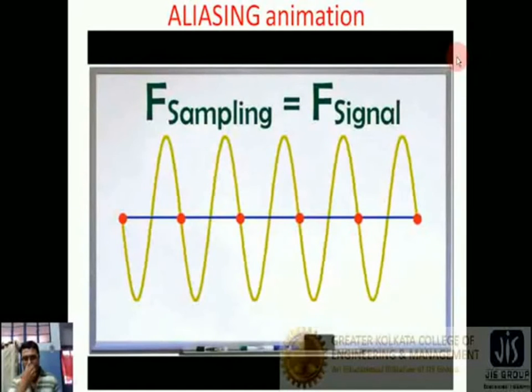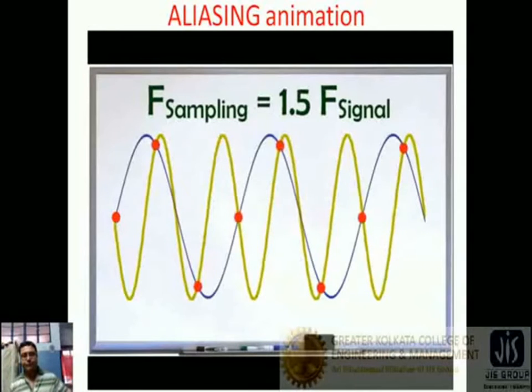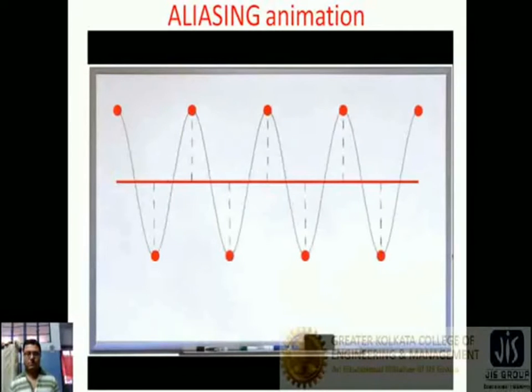The frequency of the aliased signal can be anywhere from DC up to 1/2 of the sampling frequency. According to the Nyquist theorem, the sampling frequency must be at least twice the highest frequency contained in the signal to avoid aliasing. The Nyquist criterion guarantees that there are enough sample points to properly reconstruct the signal, provided the signal is a sine wave.